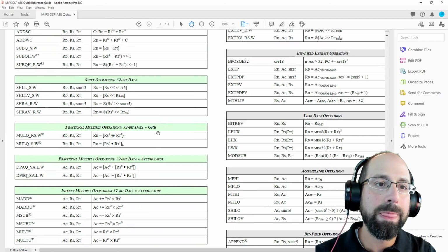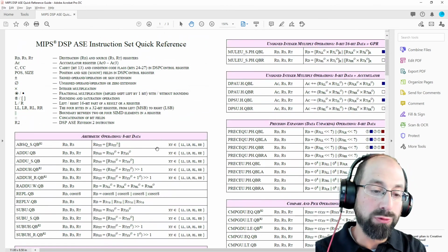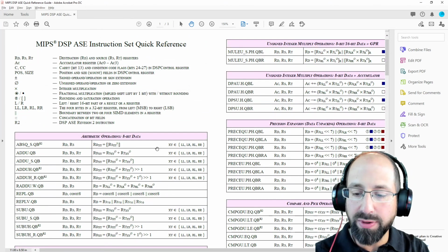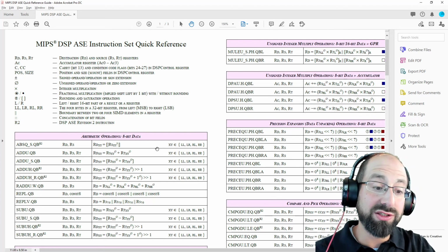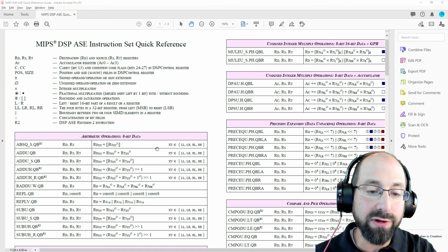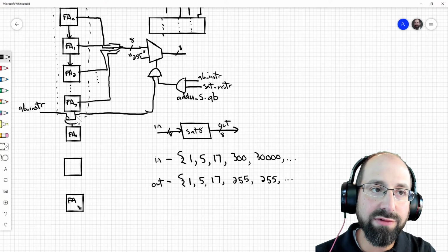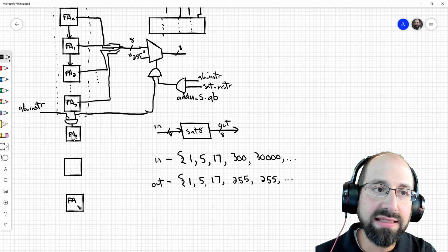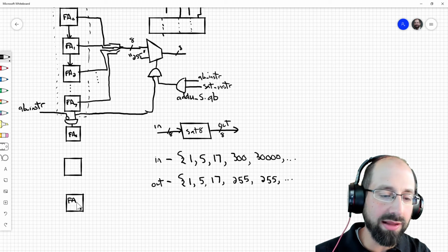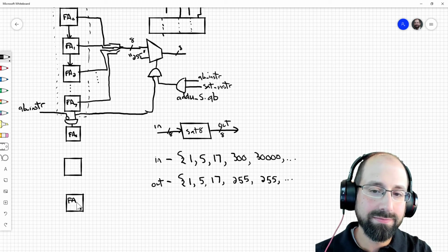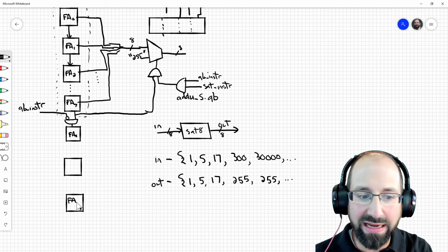It's on this sheet. But implementing, let's say, a 16-bit SIMD instruction, which would be, instead of treating the input as 4 independent bytes, treat it as 2 independent half words, would be extremely similar, right? The main difference for the 16-bit version of that same exact instruction would be, instead of having the AND gate at bit 8, bit 16, and bit 24, you would only want to engage that AND bit at bit 16. So whether that's another mux or whether that's an OR gate as an input to my AND gate, it's relatively the same thing.